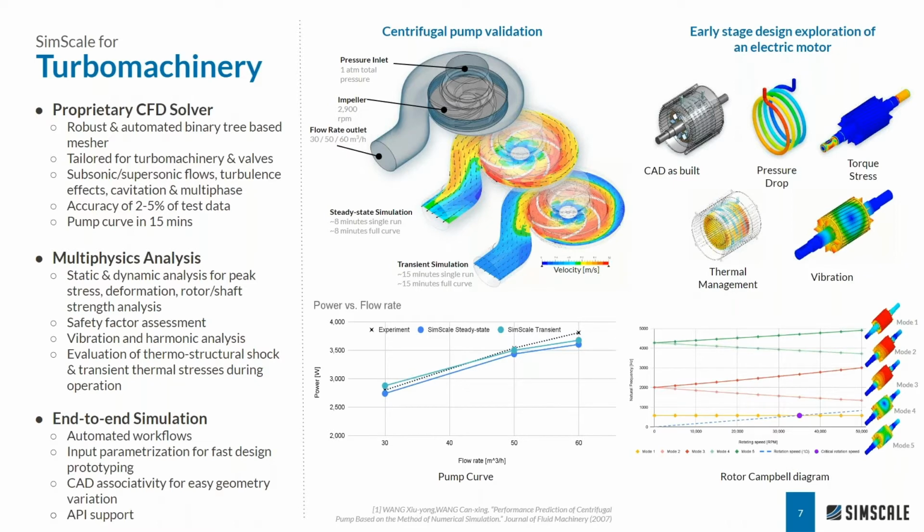So you can basically bring in one CAD model of a pump or a motor, run CFD simulations to obtain your performance curve, do a stress test or a thermal evaluation, and do vibrational analysis to obtain your Campbell diagram. So all of this multiphysics analysis is possible within the same platform.